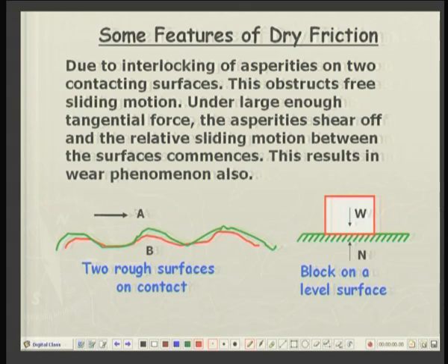Sometimes due to these asperities, the contact stresses can be so large that some heating is produced. So, there will be local melting at the contact points. Again, when we apply force, at the contact points the material will be removed or sheared off, and that is why when there are two rubbing bodies, rubbing surfaces, some loss of material is always there.